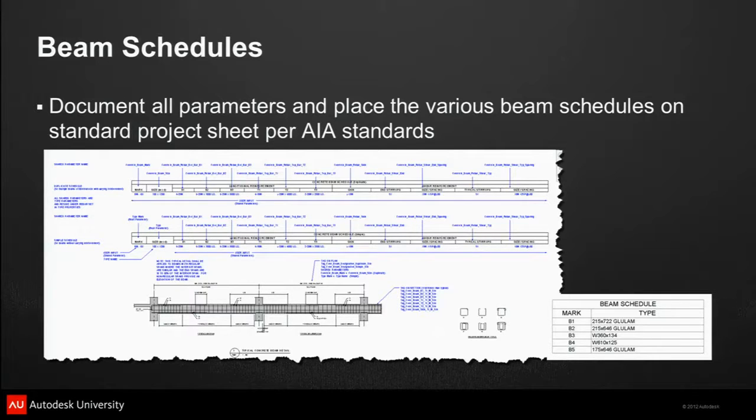We put all the information in by type. If we have some beams that are just unstandard, sloping or stepped or whatever they are, we reinforce those beams, cut a section, and add it to the sheets. Otherwise, everything is by schedule. There's a simple beam schedule set up in the template as well, by material.